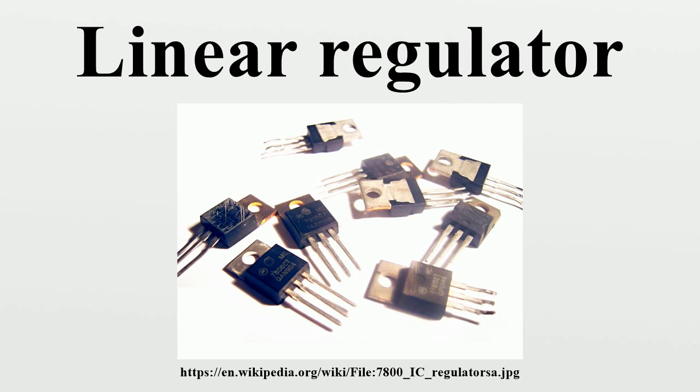Fixed regulators. Fixed, three-terminal linear regulators are commonly available to generate fixed voltages of plus 3V, and plus or minus 5V, 6V, 9V, 12V, or 15V, when the load is less than 1.5 A. The 78XX series regulate positive voltages while the 79XX series regulates negative voltages. Often, the last two digits of the device number are the output voltage. There are variants on the 78XX series ICs, such as 78L and 78S, some of which can supply up to 2 amps.